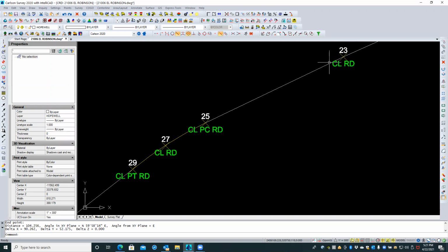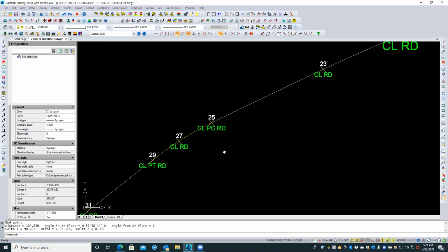I would draw this line out here and then extend that out 100, or not 100 feet. I would draw these two tangents, find my PI, and then I would come back that 100 feet. And so that's going to move this point and this point to those new locations. And then you could, or actually, no, I don't have to do that yet. I can just do this.